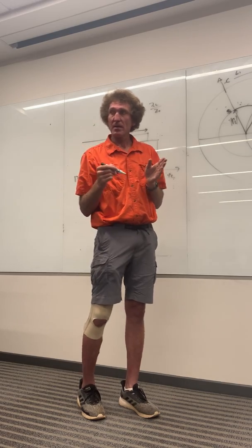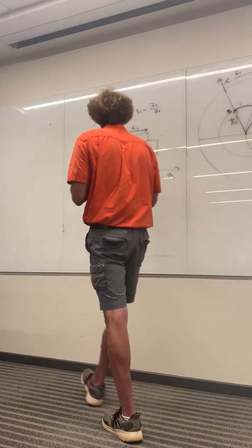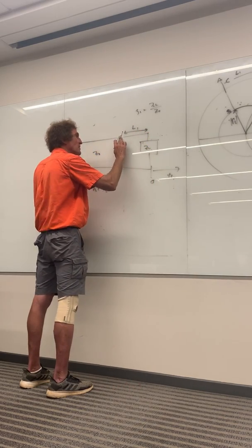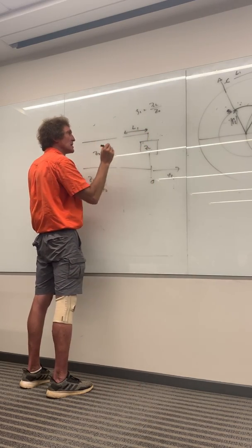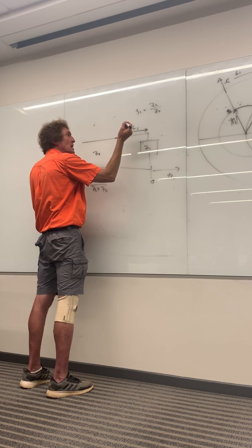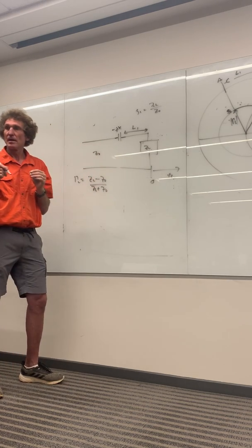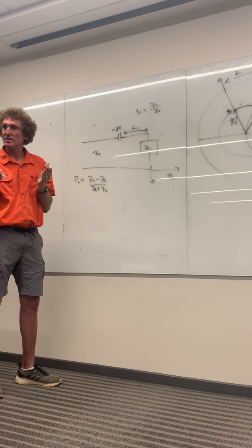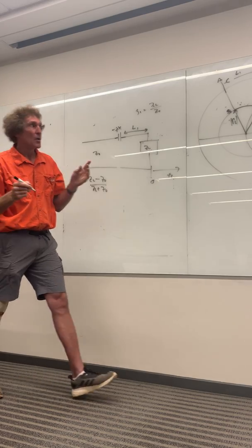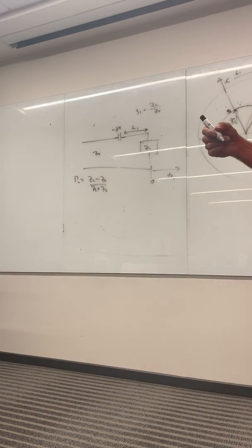All right, now, hear me. If I move to this point and I have 1 plus jX right here, what if I put an element in here, say a capacitor, that would have a normalized impedance of minus jX? Well, what happens? It's in series, right? 1 plus jX minus jX is just 1, right?